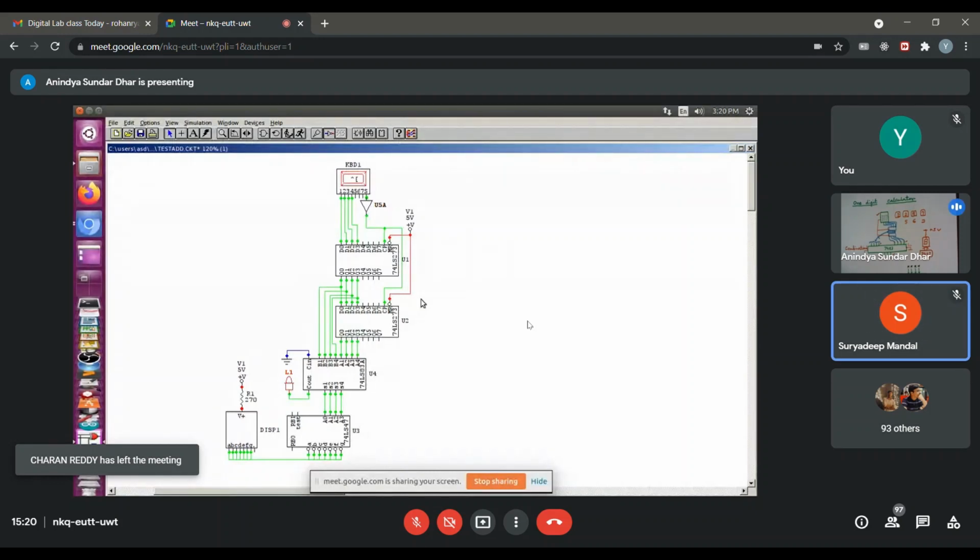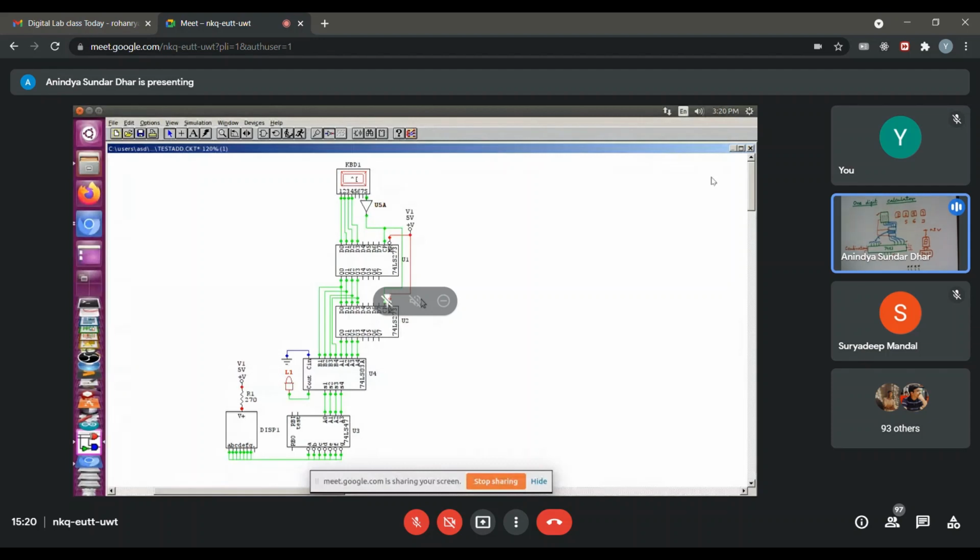Right, you are very correct. If there is a high value of external noise, sometimes you will find that it is getting reset, because noise may bring that pin to a low value, crossing the logic threshold. So just to be sure, I am connecting it to plus 5 volt, and maybe another reason is that this simulator is not recognizing that it is logic high when it is open. So in either case, I have connected it.